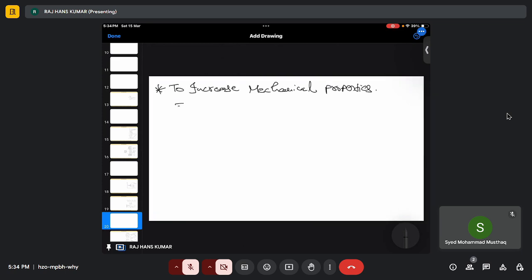So let's say the alpha phase is FCC. That means we know there are slip systems. Deformation is nothing but movement of dislocations, and for the dislocation to move, there needs to be some slip. So dislocation motion results in deformation, and it is nothing but the movement of one plane on top of another.